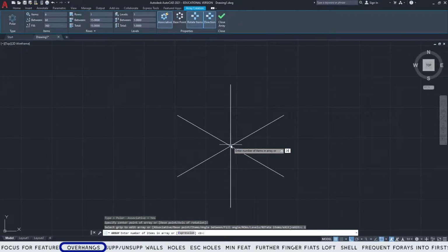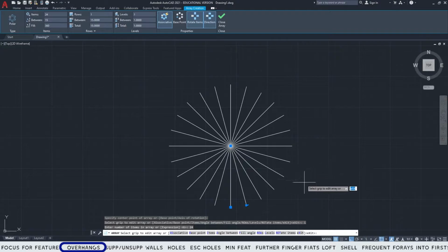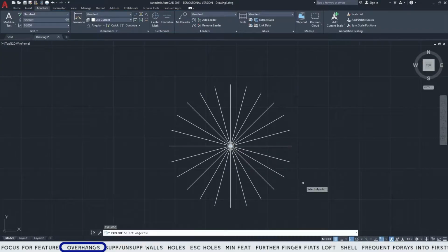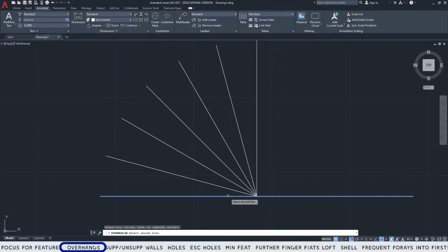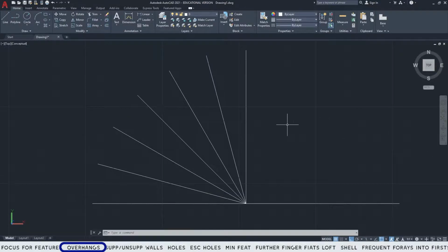Now, what is an overhang? Great question. An overhang is that part of the model that has no material underneath it when it prints. So for today's purposes, you can think of overhangs in terms of a little or a lot. Here we have a set of different angles, and when the slicer Cura considers whether supports are needed, it measures the degrees from a vertical line. So typically anything over 45 degrees is recommended.